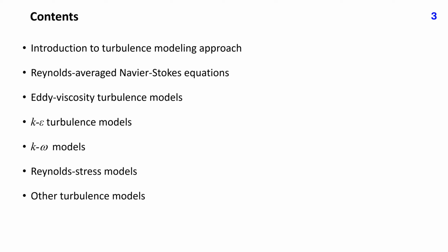Finally, the Reynolds-stress class of models is briefly described. These models solve equations for Reynolds stresses and turbulent scalar fluxes. This leads to a significantly higher computing effort than in the case of two-equation models, which is magnified by slower convergence due to the stiffness of the equation system.